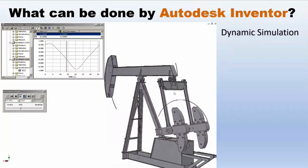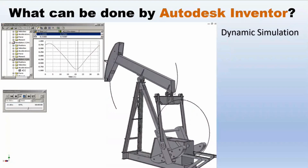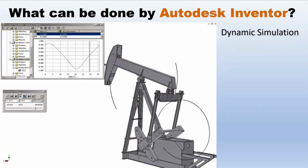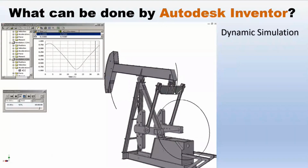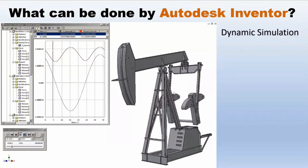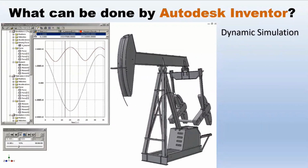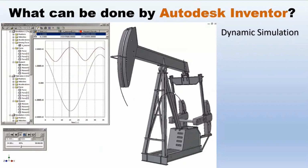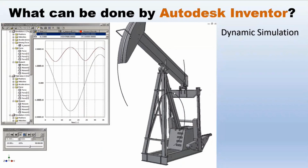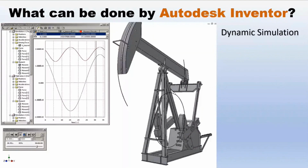Here, as you can see, you can compare the acceleration of rotation and the torque required to rotate this pump. So in the dynamic simulation tool, you can move a mechanical part, like the piston of a car motor, for example, and study the reactions on the shaft, the acceleration, the torque required, all of that. So you can study it by using the dynamic simulation tool, which is included in Autodesk Inventor Professional.